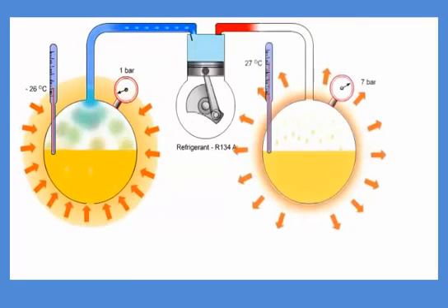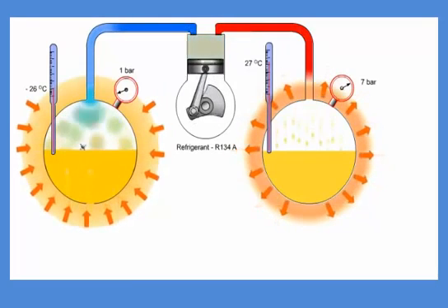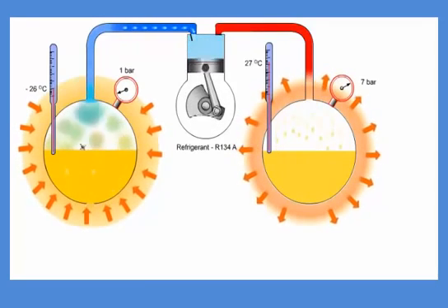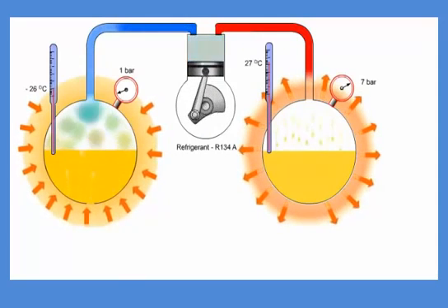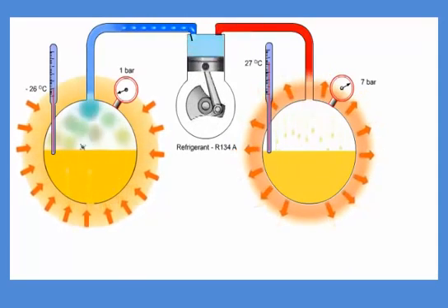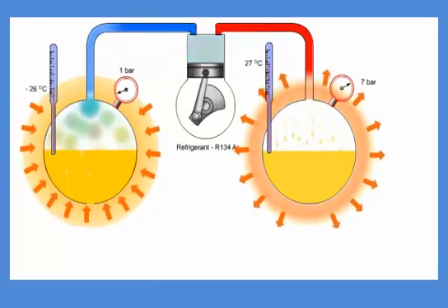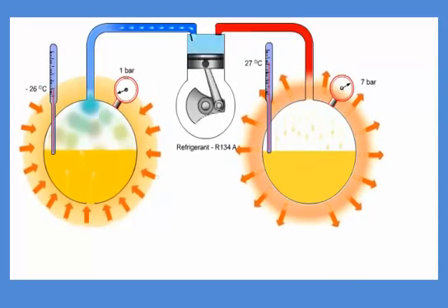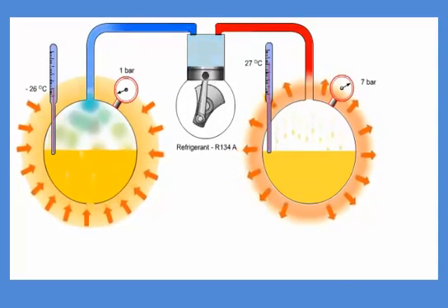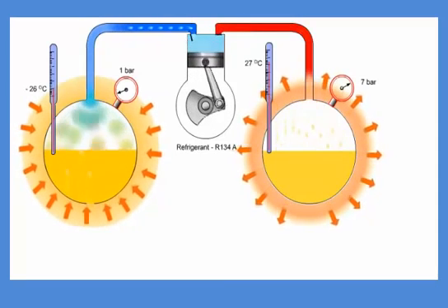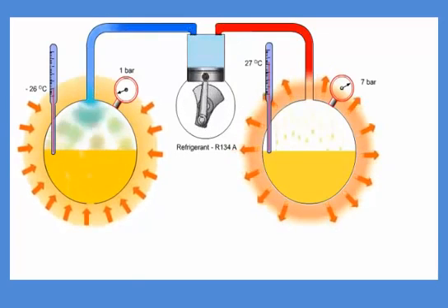You can again see the boiling refrigerant in the flask and the reciprocating compressor pumping away the refrigerant vapor, but now we supply an extra flask and connect it to the outlet of the compressor. This flask is accumulating the vapor from the compressor outlet. In this flask, the refrigerant is cooled down and will start to condensate when it comes into the flask, because the refrigerant is exposed to the relatively cold surface of the flask, which is again exposed to the ambient temperature of 21 degrees Celsius on the outside of the flask.